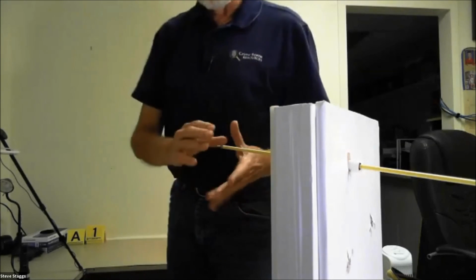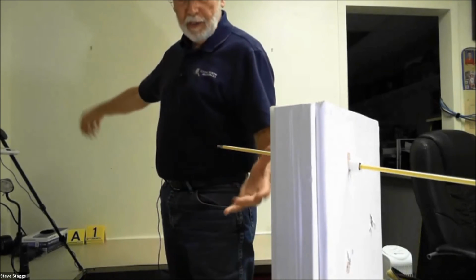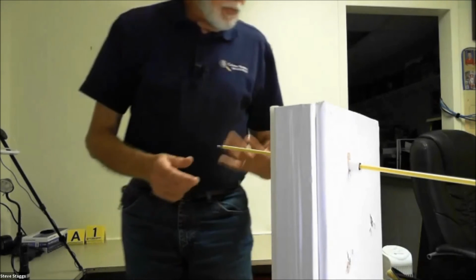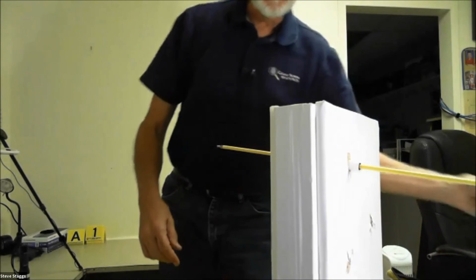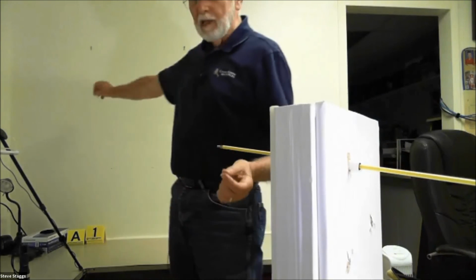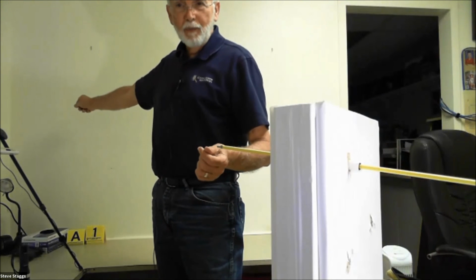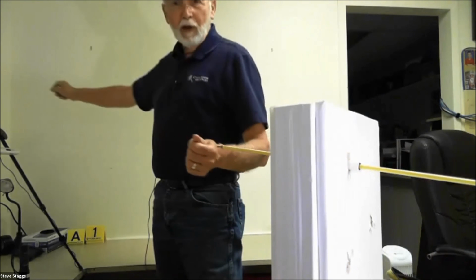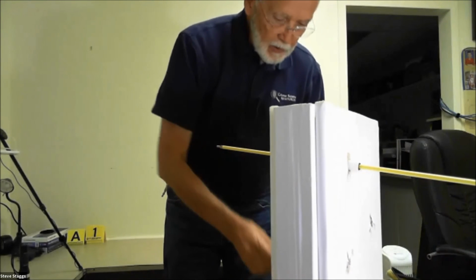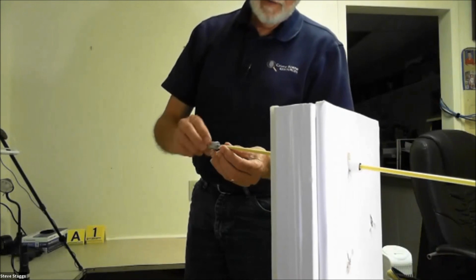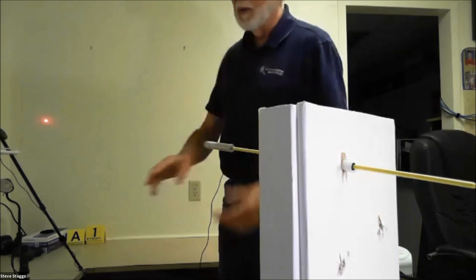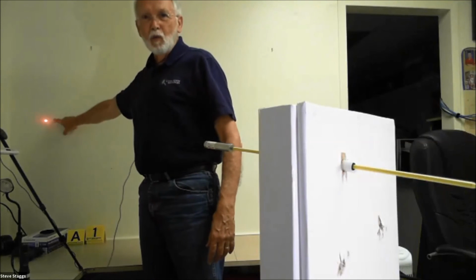But let's just go ahead and illustrate where this is by putting a string out. And really the easiest way to do this, the most effective way, is not to eyeball it and stick your string where it should go, because you could be off by a little bit. The best way is to start out with a laser. So I'm going to go ahead and put a laser. So now I have the laser on here, and it shows me a dot on the wall.